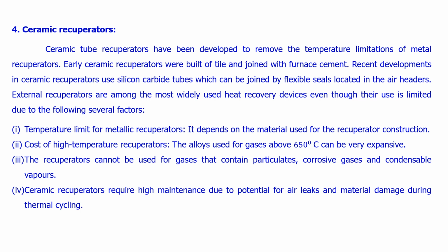Ceramic recuperators cannot be used for gases that contain particulates, corrosive gases, and condensate vapor. So this is the disadvantage of ceramic recuperators. Particulate matter, that is dust particles, carbon particles, and corrosive gases which will corrode the inside tubes, and moisture vapor, these things should be avoided.